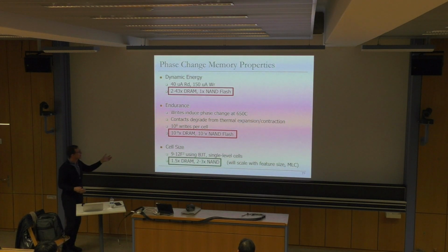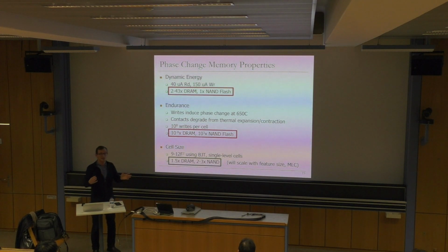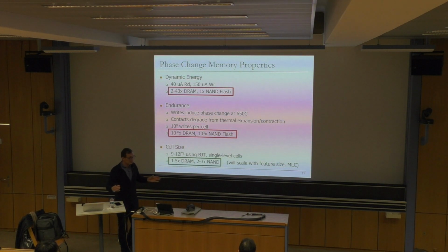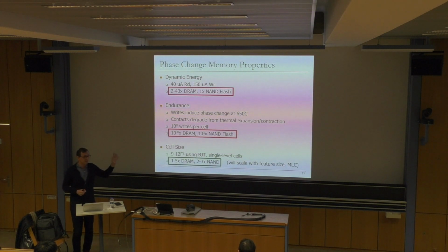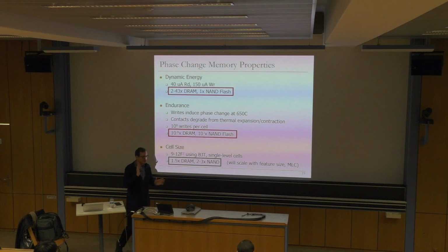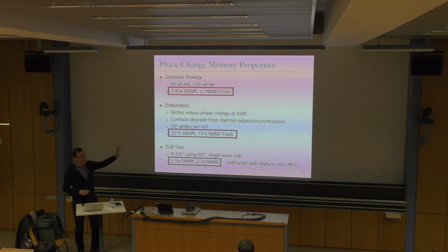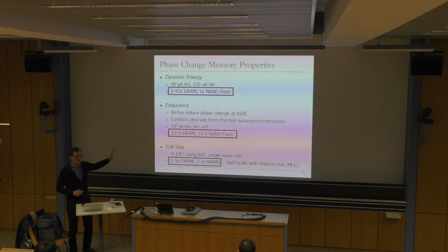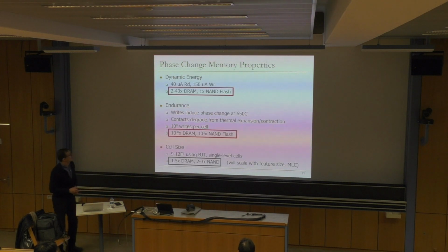There's also write disturbance that happens in these devices. Whenever you write to a cell, some other cell gets affected. That's actually a problem. A lot of phase change memory controllers need to solve this problem. There's read disturbance, not as bad as write disturbance in a lot of these devices and current technologies. Read disturbance is essentially similar to row hammer, right? If you keep reading from a location, some other locations get disturbed. So phase change memory controllers need to deal with all of those problems. And as a result, if you get a 3D XPoint memory, there's a controller associated with it, and that needs to deal with those problems. Okay, so let's take a step back.